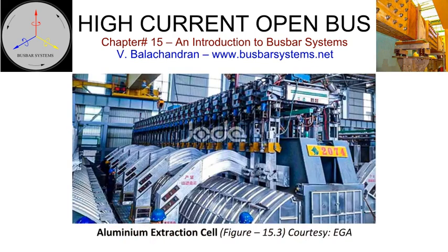For a pot line with a large number of cells in series, critical sections of the inter-cell and shorting cell connections can be manufactured at works and welded at the site. For sizing of the DC busbars, one need not consider the skin effect and proximity effect. Cell voltage for a particular metal is defined, and once the voltage drop between the two connecting ends is firmed up, the cross-section area of the conductor can be arrived at.